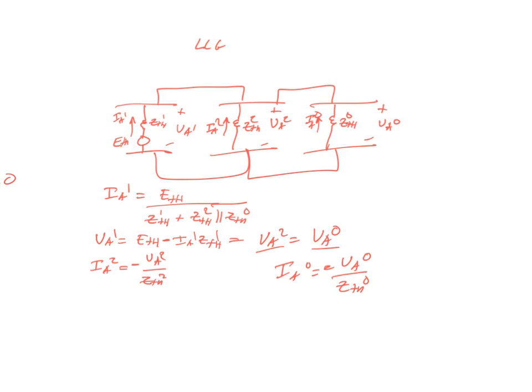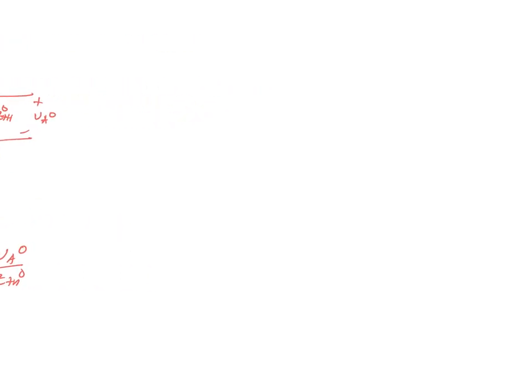So now we have our symmetrical voltages and components. We can go ahead very quickly and calculate what our phase components are going to be and back calculate from there. The only one that we haven't talked about, but it's technically not a symmetrical fault, is a three-phase fault. If we do a three-phase fault, this is really easy. A three-phase fault is going to be E Thevenin at the bus divided by our Z Thevenin 1, and this is plus to minus VA1.